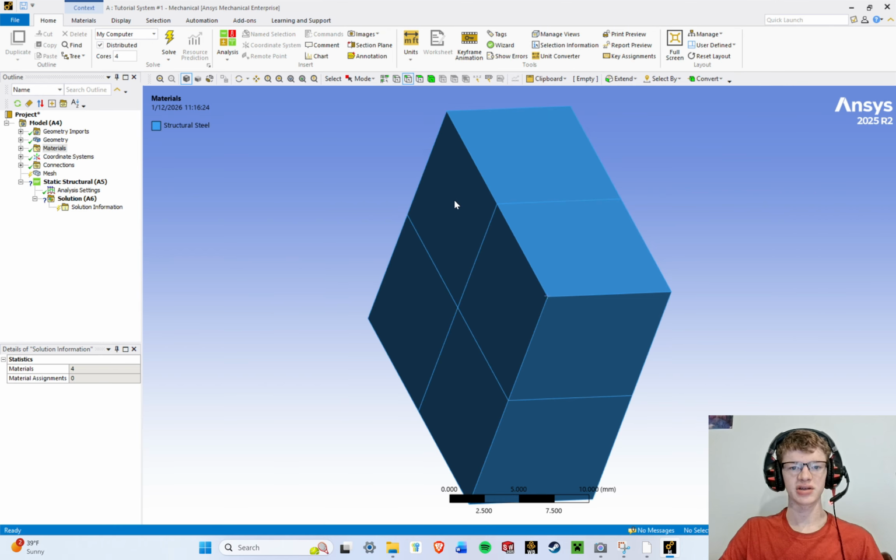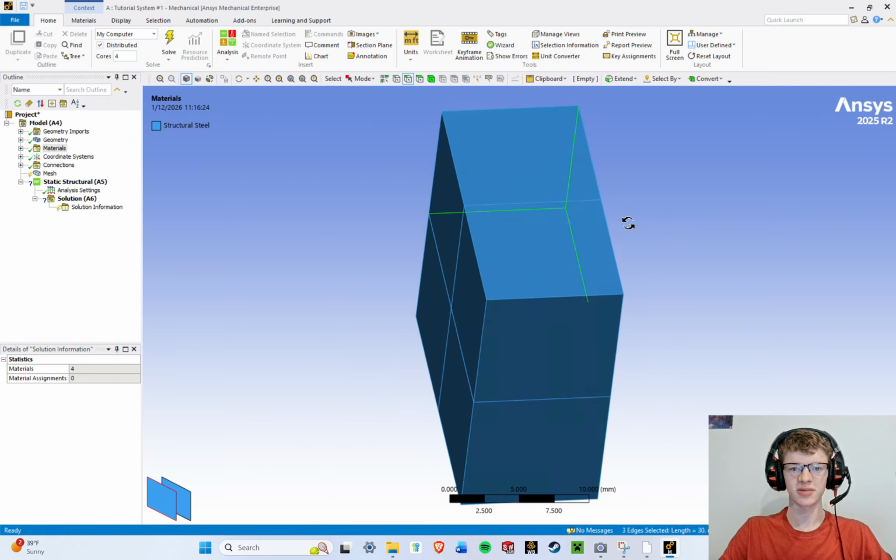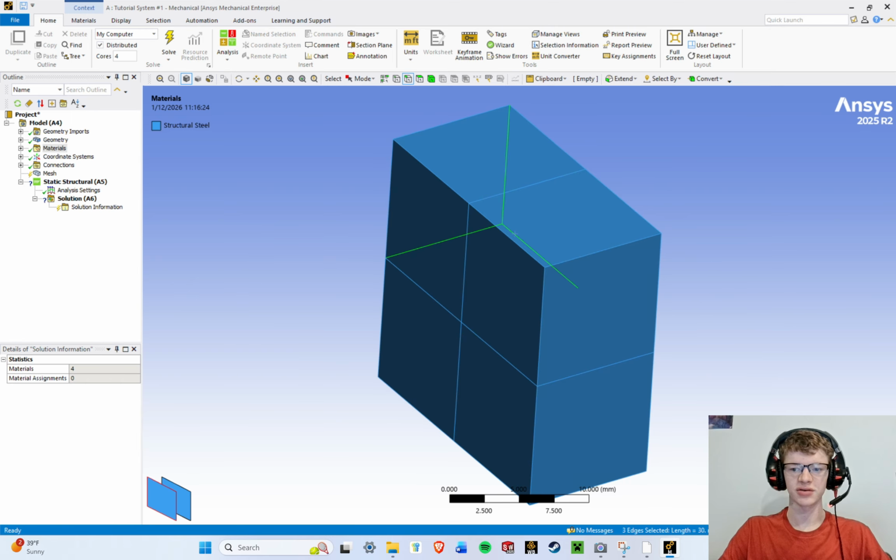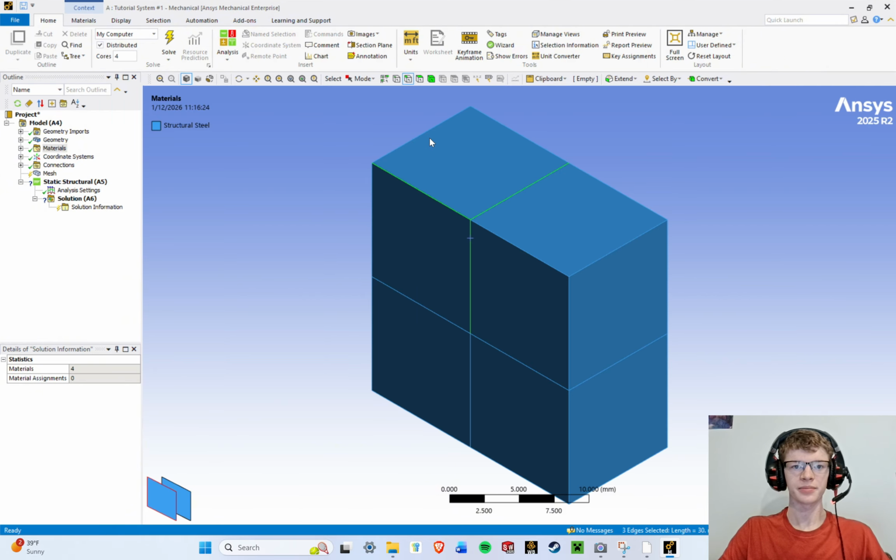With the edge, you cannot select faces, but you can select edges, and you can select edges through objects. That's rather useful. So I can select the back edges of this cube without ever having to rotate my view. With the face selected, you can select faces only, no edges, and no vertices. And with body selected, you can select bodies.